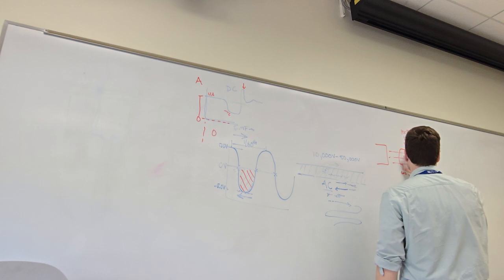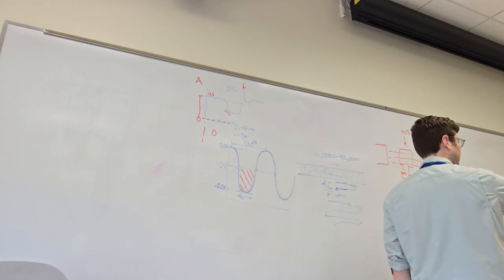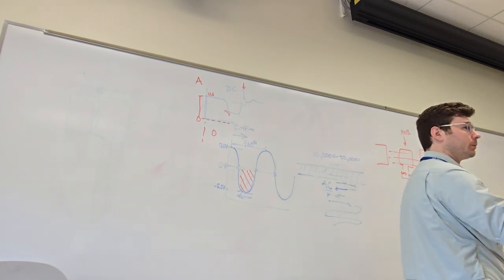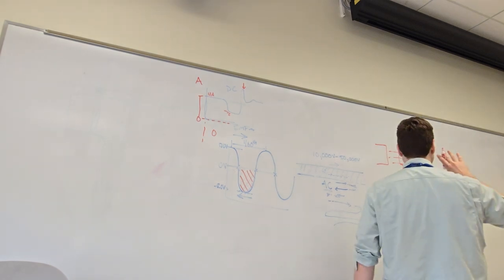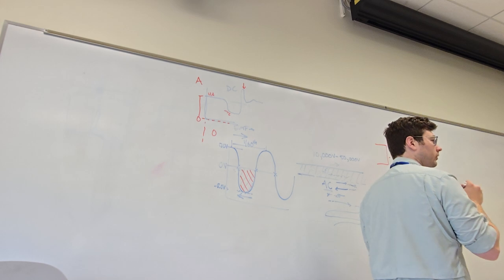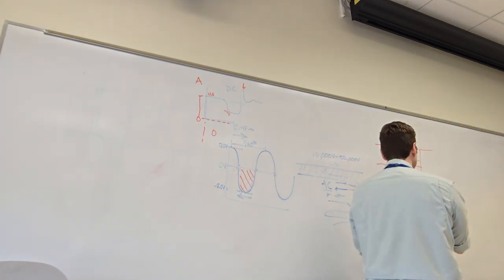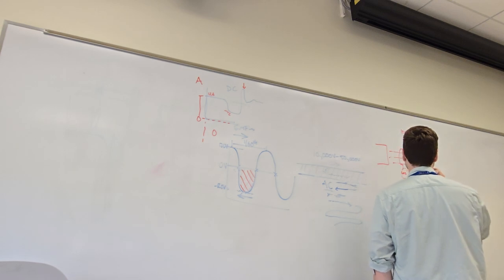At some point in the rotation, we have to have motion in order to get this voltage. This coil can't just sit in this field and generate electricity like a perpetual motion machine. It has to have some sort of force that causes this to turn that will induce this voltage. That is our generator in action. The armature, some force will cause this thing to move within this field.